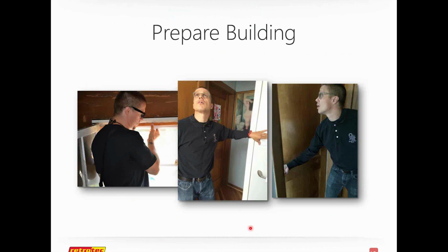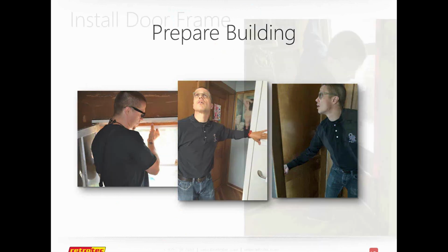So it's very important that we have the outside doors and windows closed, the inside doors and windows open, the fireplace shut off, or sometimes, with the fireplace, if you want to make sure that you're testing that hole, because that is a hole in the shell and you want that to perform, you want to test it as it is. Sometimes I've known people that say just take a newspaper and get it wet and put it on the ashes. But yeah, make sure that furnace is turned off on the boiler, so you don't pull any smoke. Thank you, Mr. Burroughs. Good point. But yeah, you want to make sure that furnace is off too. All right? Any questions about that?